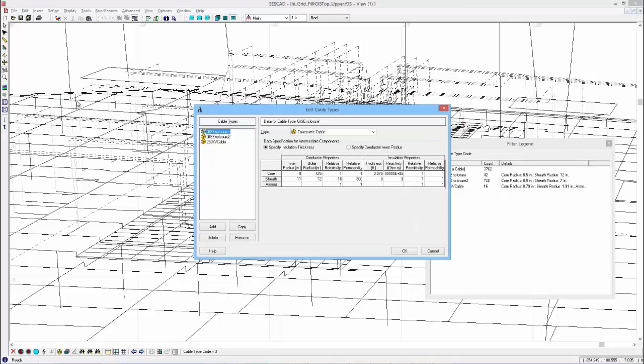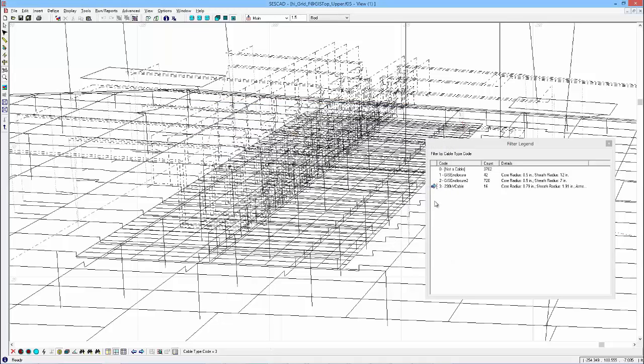We have two different radius enclosures defined. Here the enclosure is defined to be the sheath of this cable and is not insulated. We have a 12-inch radius enclosure and a 7-inch radius enclosure. The underground 230 kV cable has a core sheath and armor, and the armor conductor is insulated. The enclosure is grounded at its two ends, outside the GIS building, but also grounded densely, maximum 8-foot separation distance, at various locations along the length.